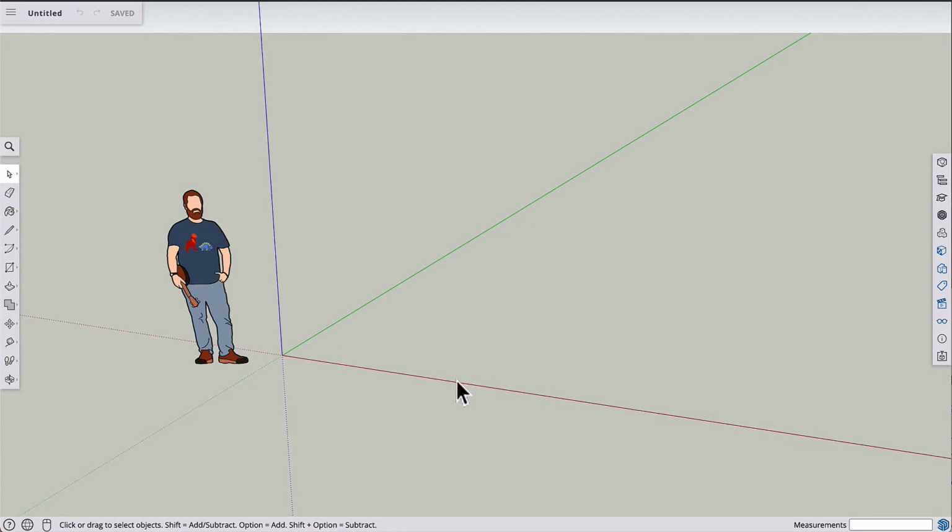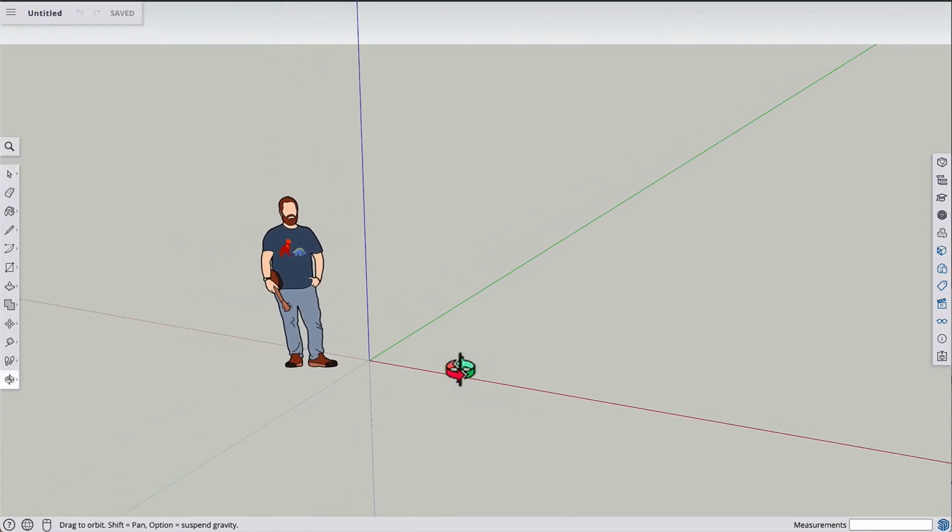In this lesson, we are going to learn the best ways to navigate inside SketchUp. On the left side of the screen is the tool tray. This houses all the various tools available for drawing and creating geometry inside of SketchUp. We'll start with the rectangle tool. Click your mouse or trackpad once to start, pull away, and click again to finish.